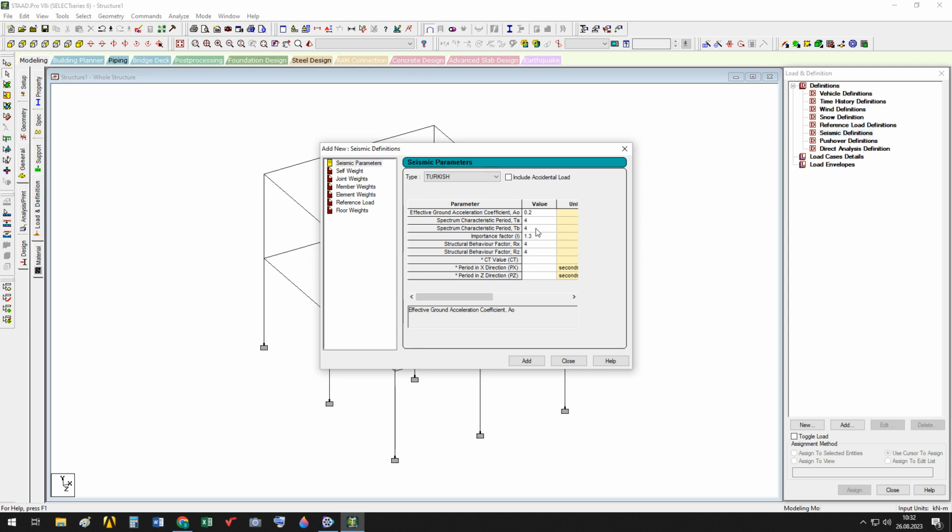In Turkey, there is a website. You enter the latitude and the longitude of your structure and select its ground type, and all those values are given to you, and from tables you can obtain all those values. This coefficient is used to reduce the earthquake acceleration. Earthquake acceleration is taken from the lateral earthquake acceleration design spectrum and divided by R.